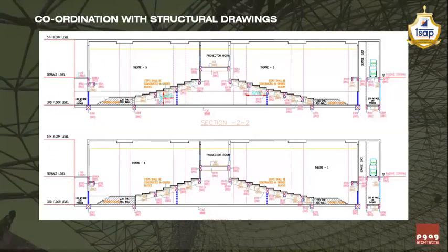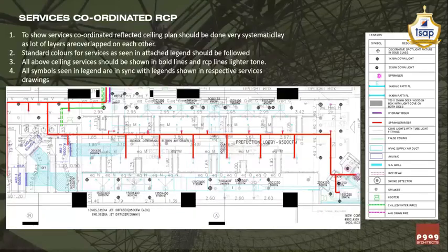It is not possible for you to go and measure all the dimensions of the site every time. But once you do a first site visit, you are supposed to check a few dimensions and later correlate your structural drawings, then existing photographs, and sometimes actual dimensions, and then go ahead with the actual false ceiling drawing of your space.